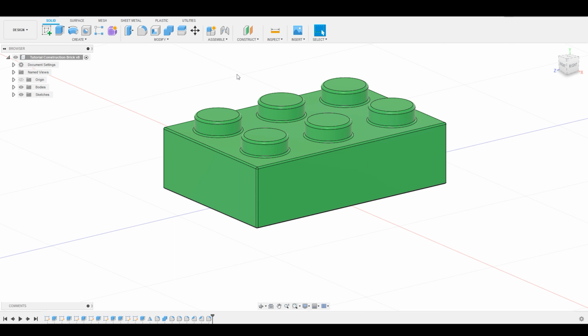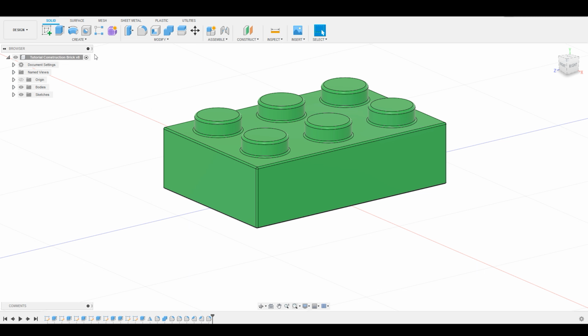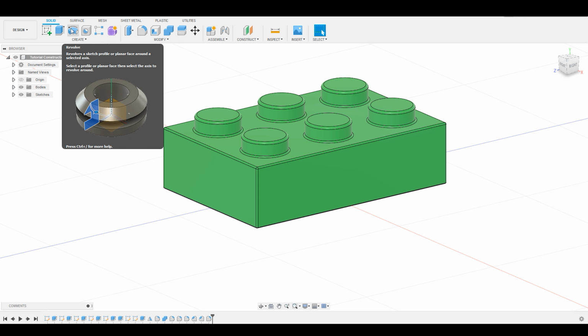but in order to help us create our rounded shapes, we're not necessarily going to do a bunch of extrusions. That seems like it's kind of tedious and time consuming. What we're going to do instead is use our Revolve command. And as you may assume from the description, the Revolve command acts similarly to the extrude command in that you are taking a flat profile sketch and you are rotating it around an axis. And so what we need to do is create that profile.